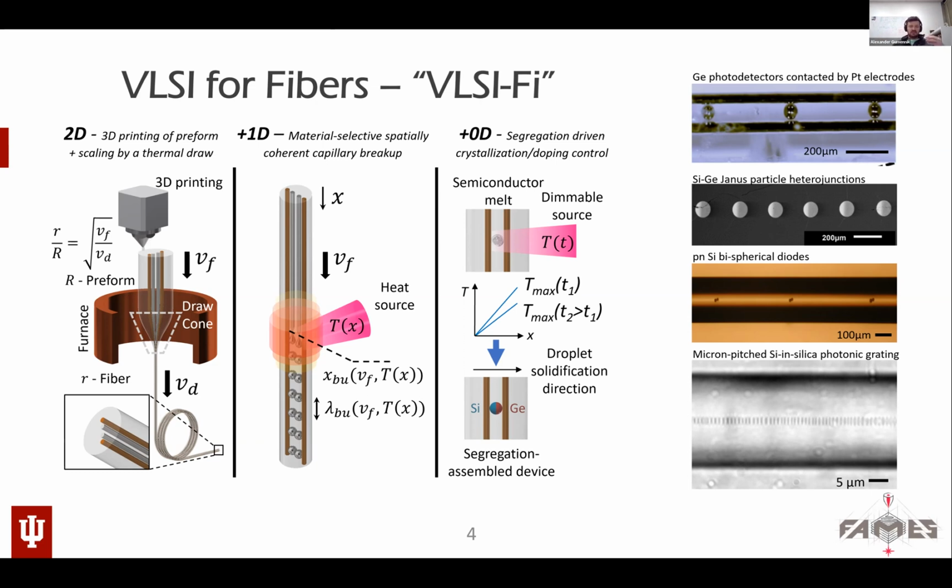And resonance structures are created by those photonic gratings, okay? And waveguides are just continuous cores. So since we can create waveguides and can create resonance structures, we can create any combinations of those. And one of the advantages of a fiber draw process is that any material that is liquid at the draw temperature of the glass, which is 2000 degrees, if it can be kept from chemically reacting with silica, can be drawn into a core.